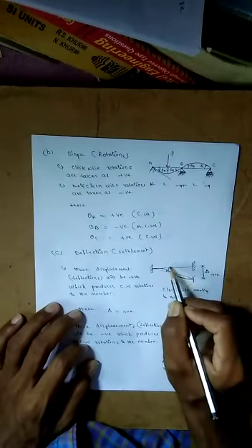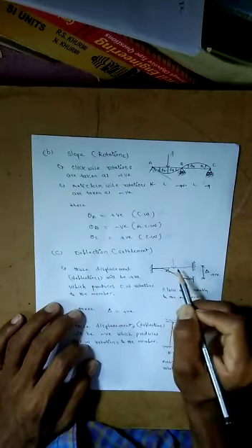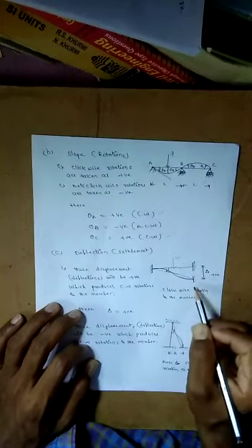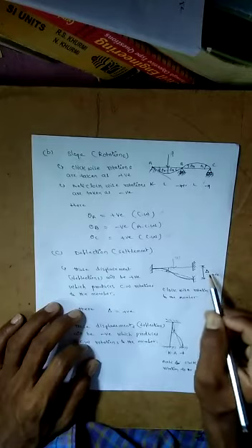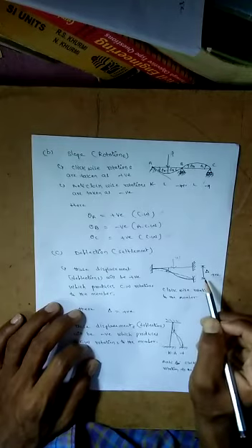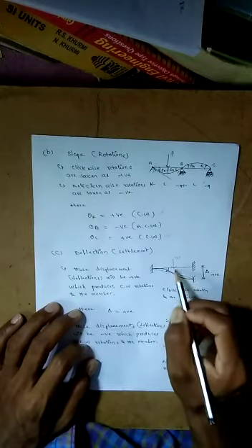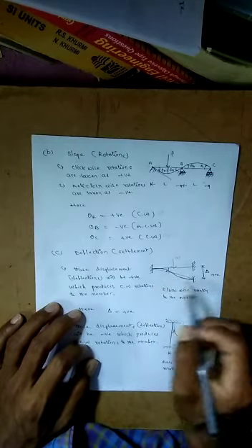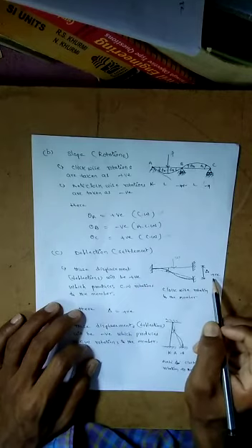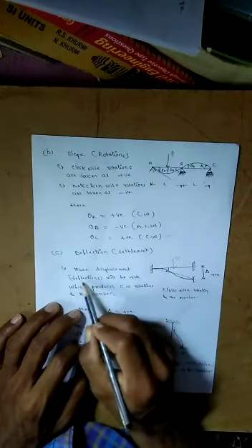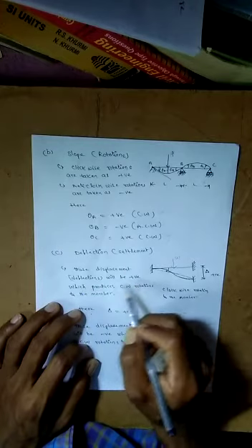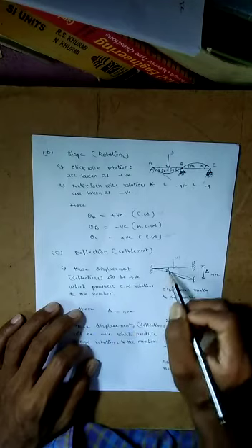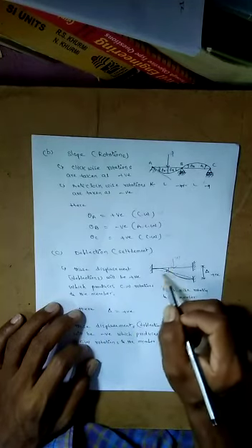Now deflection, that means settlement. For a fixed beam, I take a simple load W here. The beam is deflected or settled by some amount delta. How do we take it as positive or negative? When the member rotates in the clockwise direction, that is positive delta or positive deflection. The displacement, that is deflection, will be positive if it produces clockwise rotation of the member.